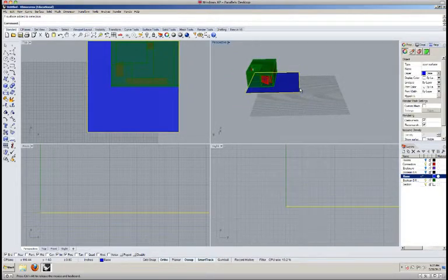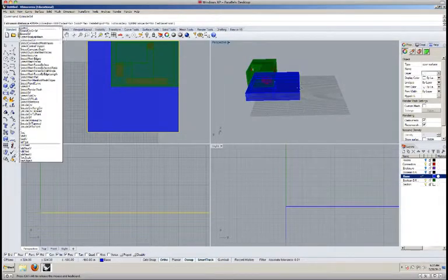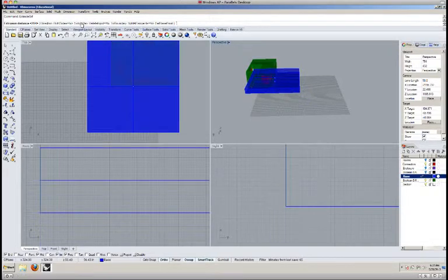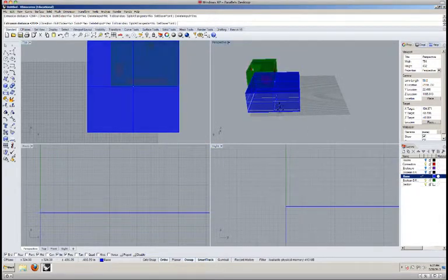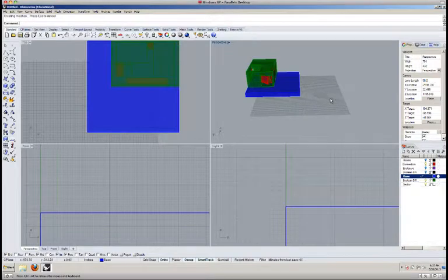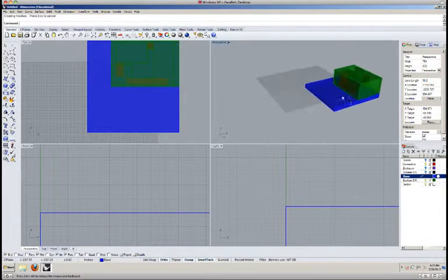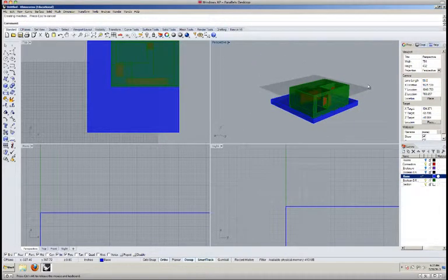Regardless, I need to turn this plane into a volume that's 4 feet deep, so extrude surface. I want to extrude it as a solid, yes, but this time I want to turn off the delete input. I want to turn it on, I'm sorry, I should say, because I don't want to keep the surface and have a volume. I want just one or the other. I'm going to extrude it -4 feet so that it goes down, and I've got my object. So in the next tutorial we'll talk about how you start to turn this into the drawings that you need for class.